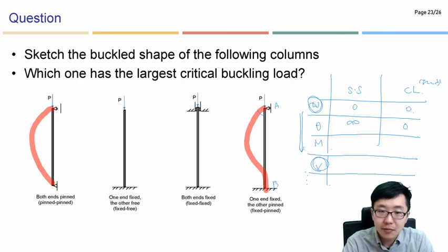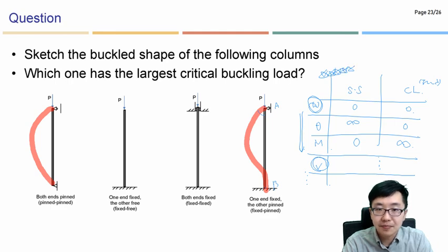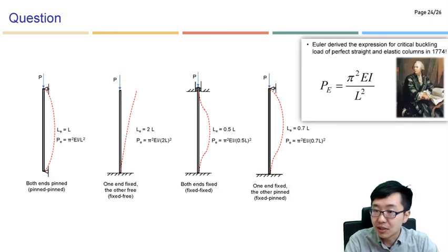And based on this slope information, we can see that this moment for simply supported case, this is moment free condition. But here, the maximum moment will be applied, to not allow the slope here. So maximum, right? So please have a look at the simple beam theory part. And the shape will be, for example, like that. Simply supported, one fixed, one free, and fixed and fixed, and fixed and simply supported condition.